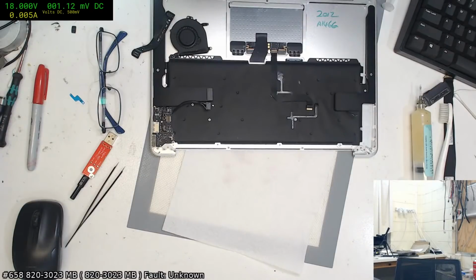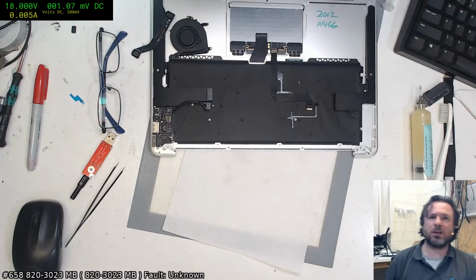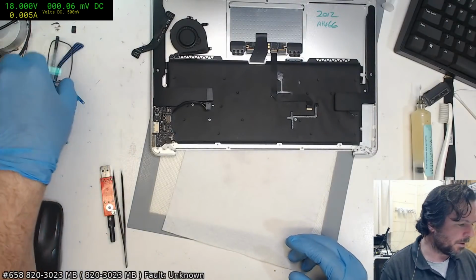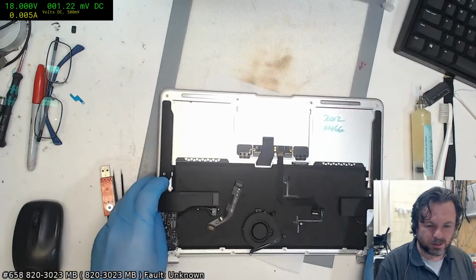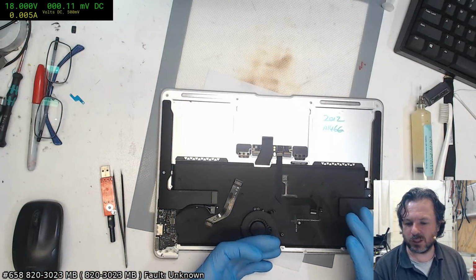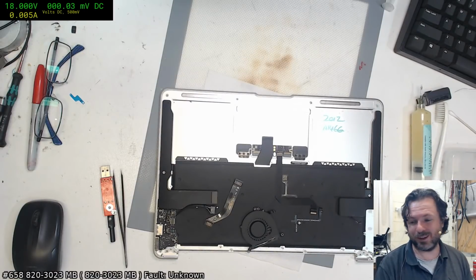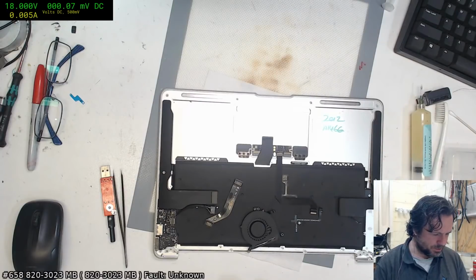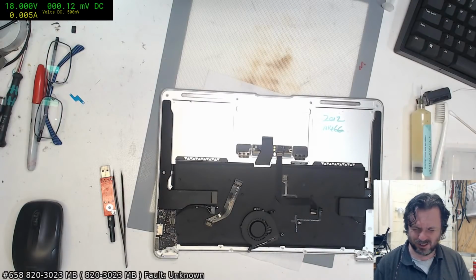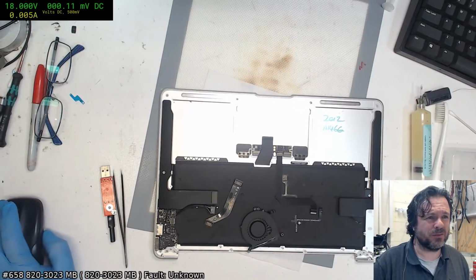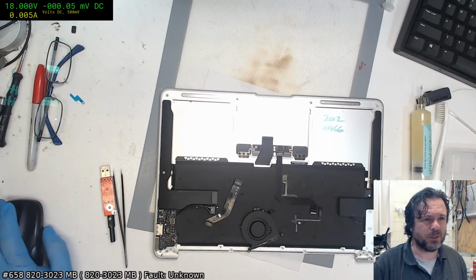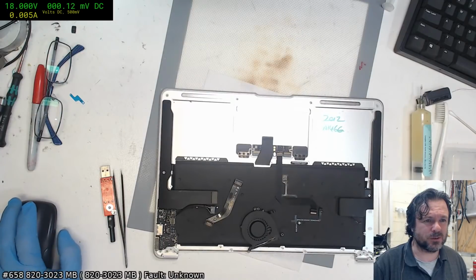Now, it's the way it goes, you know. When people say to me they've got these 3023 boards, it's usually like, okay, there's a pretty good chance that they're not going to be repairable, or it's not worth repairing, but we'll give it a shot. But yeah, this is why on eBay and things like that, if you see a 2012 1466, you just run away, because I think there is a board that isn't too bad. I'm trying to think what it is. Is it 3209 or something? I can never remember. But the 3023 seems to be just murderously bad.